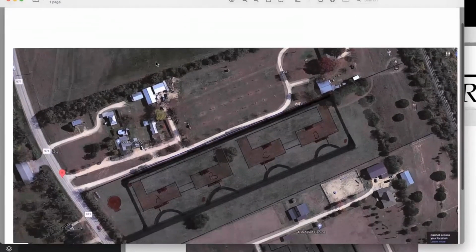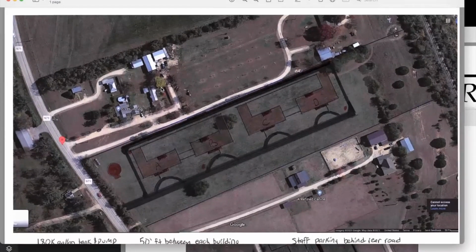This is the next drawing, and this is closer to current, but it's not quite current. I have my road coming off the street here, and here it allowed me to get close enough that I can bring it to a civil engineer and say, hey, here's what people are wanting, and here's what I want. Some of the things that he said were about fire hydrants. He said, I need a fire hydrant within 500 feet of everywhere. So we literally started measuring things out. Between here and this one, it's less than 1,000 feet. So if you're over here, you're within 500 feet this way, or within 500 feet this way. The same as you go this way. Here's one here and here, right? So those are some things to consider.